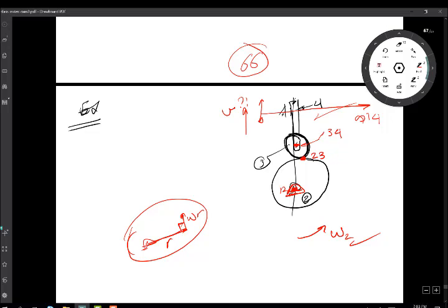This is the cam. Cam is like that. So if I find a point on it and it's 2, 4, for example, then I just draw perpendicular to the line, and then this will give me the velocity of 2, 4. And if it's called 2, 4, it falls on 2, so it will be on 4. So there's the velocity of 4, which is the follower. This is the strategy I'm following. So now let's see how to get to 4.